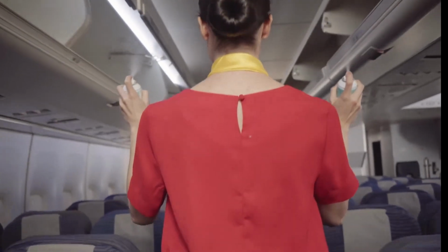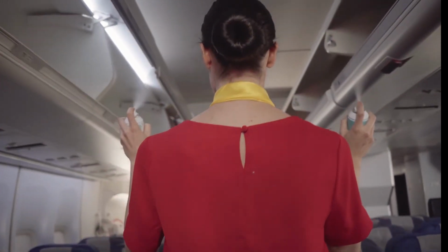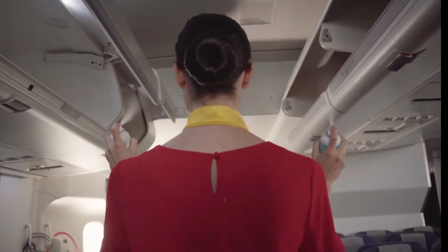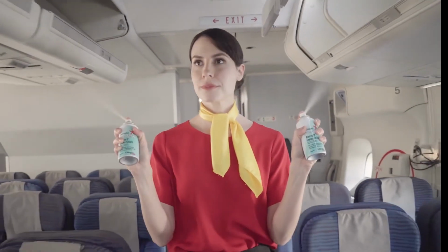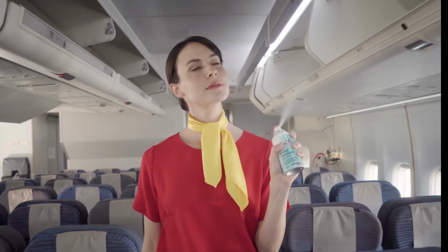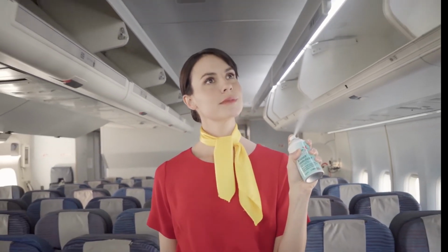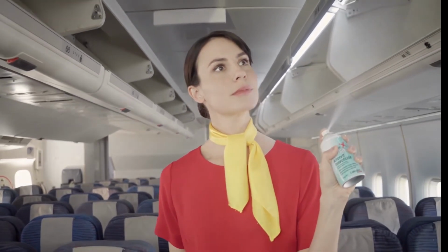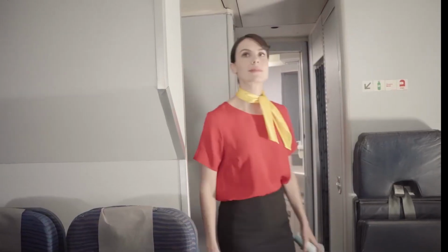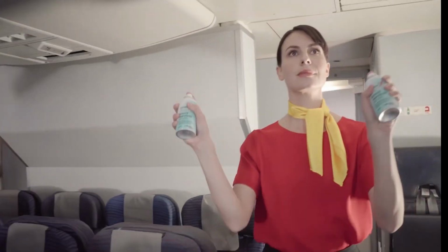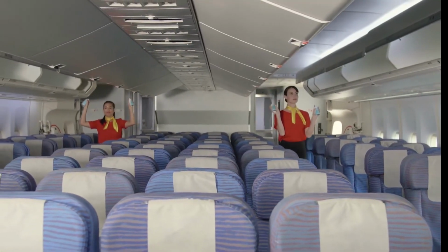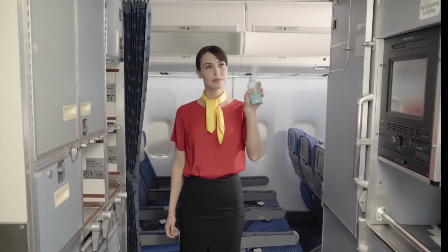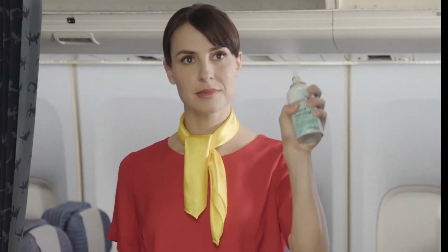If your aircraft requires 3 cans to be used down the aisle of the main cabin area, follow the same application method by first holding 1 can in each hand. Then, when these cans run out, collect another full can and continue spraying from the point you stopped, moving in the same direction. Should 4 cans be specified for use down the aisles of the main cabin, it's best that 2 crew members carry out the treatment. Spray all galleys, including those on the lower levels and lift access areas.